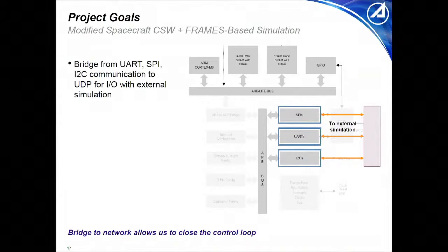So you can talk to other devices that you might have defined in QEMU, but it doesn't really allow you to punch out of the emulation and into the external world, which is what we needed to do because our 6DOF vehicle model sits somewhere else. It's a separate application. It runs separately. It could be running on a separate machine, or right next to you on the same machine. But either way, it's not in QEMU. So we had to think of a different way to get this data out of QEMU's virtual machine.